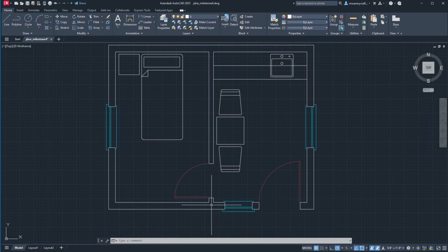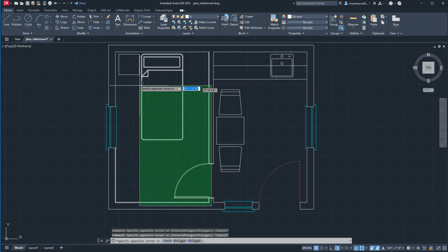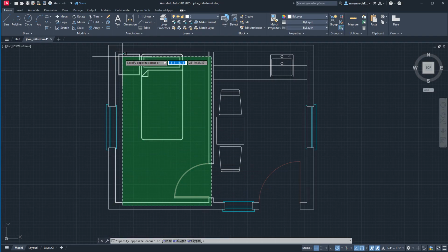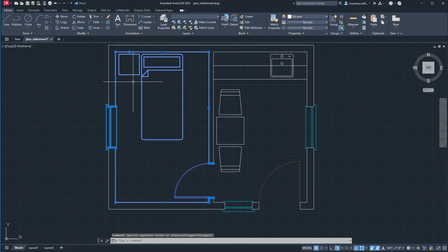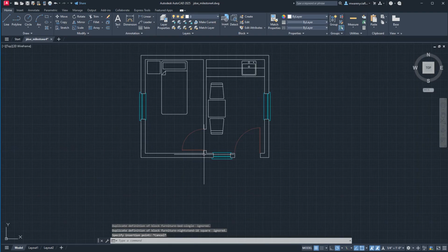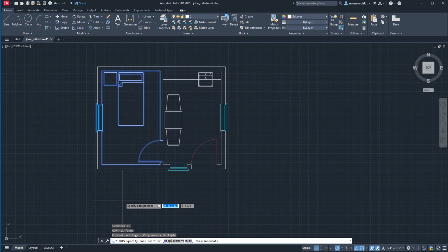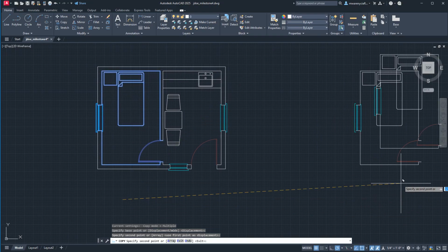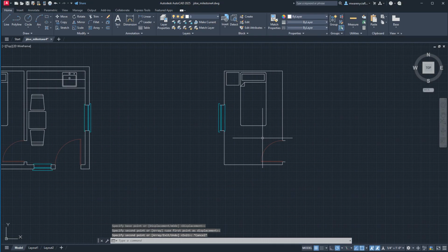And what I want to do is grab everything that touches this wall. So I'm going to start inside here, and we're going to go right to left. And you can see we're picking up this door, the bed, this nightstand, the window, but also all the wall surfaces. Okay, so I'm going to do that selection, and then I'm going to copy it. Actually, let me do a copy CO, and we'll bring this out here, and this will be what we use.